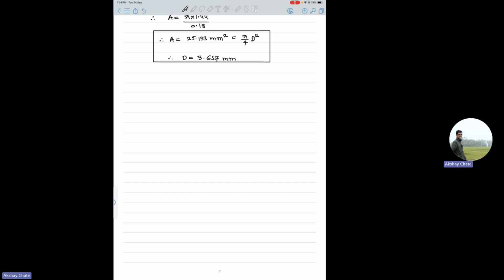Okay, that is fine. But if it is a fusion welding, there will be two phases, liquid and solid, and in between there will be a mushy zone, because in most cases the liquid gets solidified gradually. There will be a mushy zone in many cases, because you typically deal with alloys. You generally don't deal with pure metals in reality.